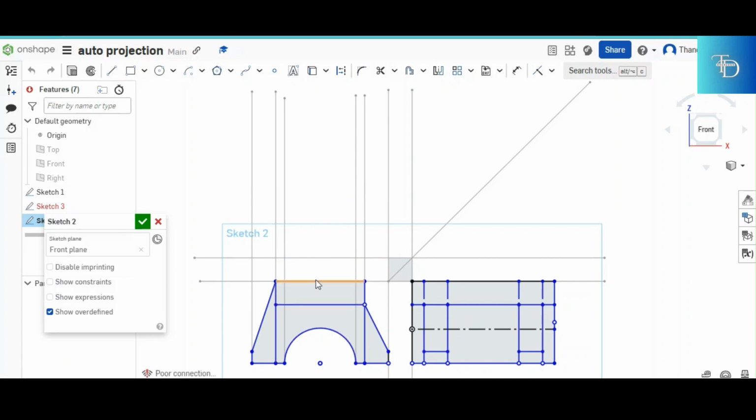Now the next thing you do, your side view should also do the same. But how do you get your dimensions from the right view to that area over there? The same thing applies. You project all the dimensions from the side. But how do you do that? That's where our 45-degree line comes in. Our 45-degree line helps with what? With projecting from the side view to the missing view. So after projecting to the 45-degree line, once you touch the 45-degree line, that's where you stop.